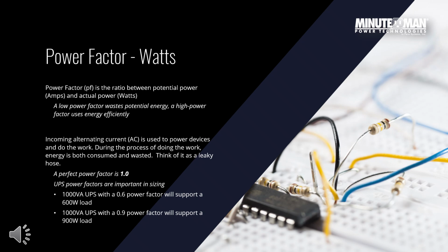What's an ideal versus a poor power factor? An ideal power factor is 1 or 100%, meaning all the power is being used effectively. A poor power factor, i.e., 0.7 or 70%, means you're paying for power you're not fully using. Why does power factor matter? Well, 4 simple reasons. Number 1, cost savings. Using devices with a low power factor means you're paying for energy you're not getting the benefit of using.